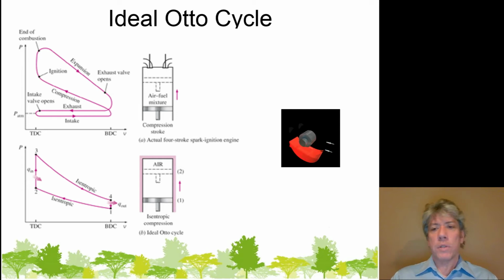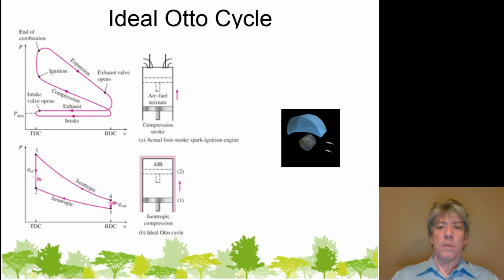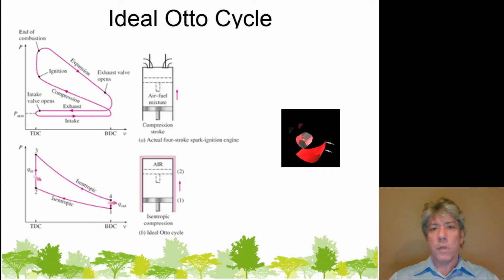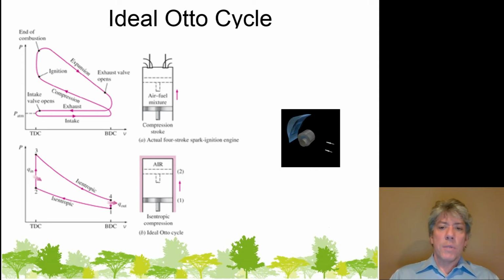One of the reasons the Wankel was so powerful is because you only see one side of that roughly triangular shape. There were actually three at the same time, so one rotor was acting like three pistons essentially. So in a very small engine, you could get essentially the performance of a 6-cylinder engine, which was pretty good. And then if you soup it up, you could really squeal the tires with this thing. So while we can't even differentiate with this idealized Otto cycle between a rotary engine and a piston engine, which probably seems like pretty rough resolution, while we can't differentiate between the two, we'll still be able to say something interesting and useful about both.